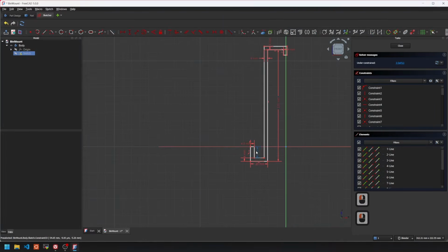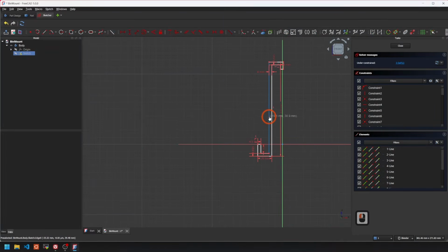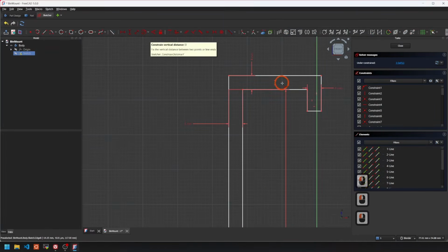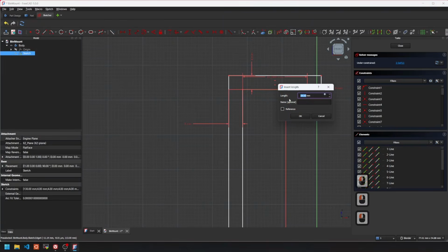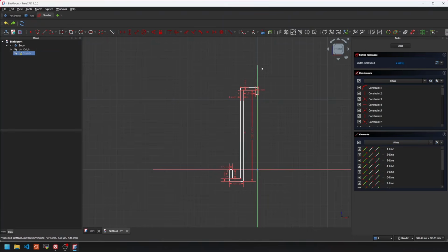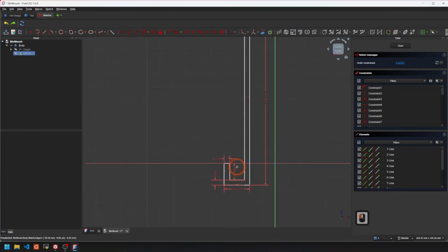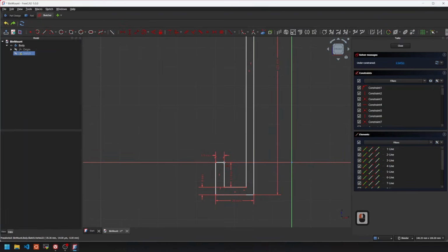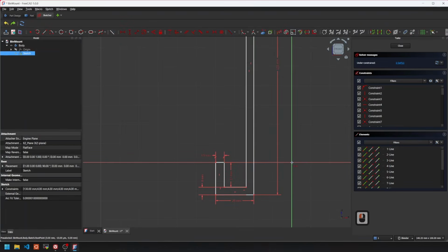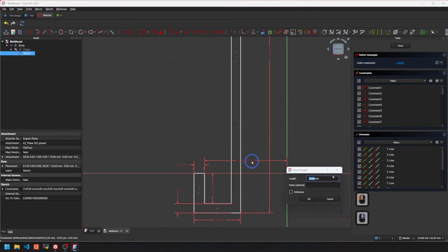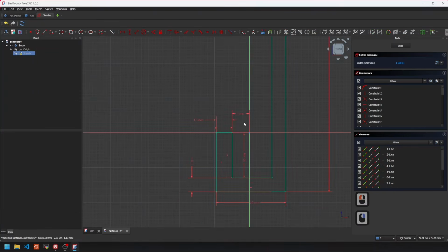And now what we are missing is only, now we need to add the constraint to the bottom, because this one is 70 millimeter. Right now the shape is actually fully constrained, but we can still move it around because it has no reference, and we set the reference. So we say I will choose this point and then basically the point 0, 0 in this grid. And I'm going to say this should be like 5 millimeter. Where is it? 5 millimeter.